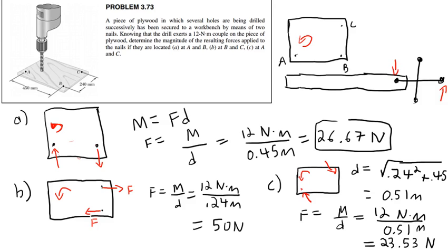What's the one thing you've got to be careful of though when you're using a long cheater bar? Smacking your hand into something? Smacking your hand into something, that could happen. No, actually, one major problem is, if you say, well, if a 3-foot cheater arm is good, a 30-foot cheater pole will be even better. Well, you might just come along and shear the head right off that bolt, and then you're going to have a real bad time. Anyway, that's not going to be a happy day. Okay, so that's that. Any questions on this?